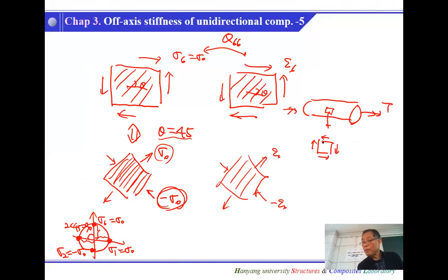So it is better to have fibers this way, at 45 degrees. But one way of 45 is not that strong. You need to have the other way 45 as well. So to make a tube that supports torque strongly, have plus 45 and minus 45. Okay, so 45 is the very typical angle to enhance or maximize shear stiffness.